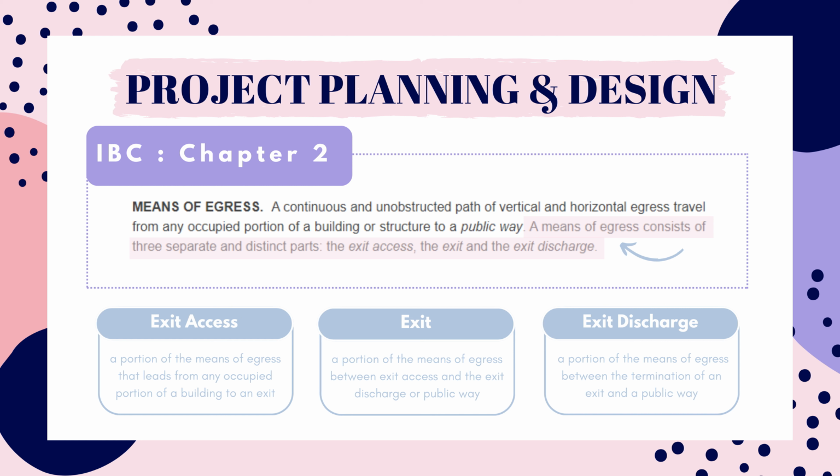I will admit I put that stair option in there to try and trick you. A stair could be part of the means of egress, but it would be designated as an exit access stairway. Not every stair is part of the means of egress. They are most of the time, but not always. So make sure to specifically answer the question. If it's wishy-washy, then it's probably not the right choice.